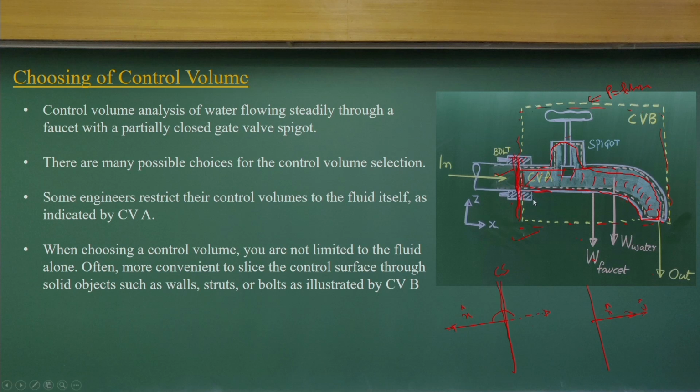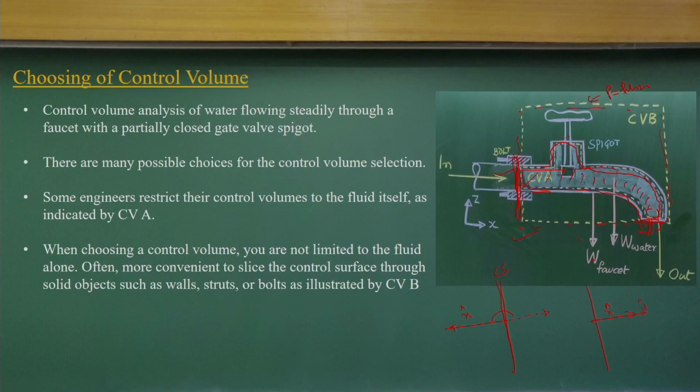That is what my point is. We can consider the control surface with respect to velocity. We can take any arbitrary shape, but when you take arbitrary shapes, if V and N do not have 0 or 180 degrees, you will end up doing a scalar product and surface integrals to solve the problems, which is more time consuming and laborious, but the results will be the same.